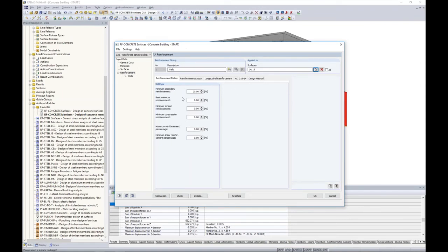The reinforcement ratios, well, there are some default settings here. For example, maximum reinforcement percentage is set at 9%. Well, the ACI standard actually tells you that for surface reinforcement, we're actually more concerned with the strain being less than 0.004 rather than a specific percentage called out. But you can adjust this percentage as a user in order to make sure that we have a strain that's below what the standard tells us to.